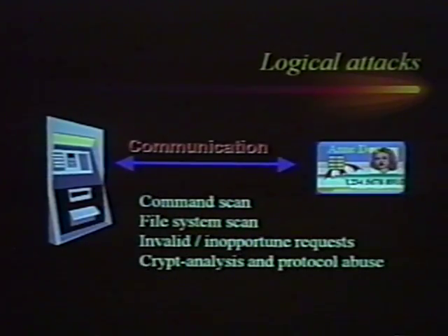Smart cards use binary coding of commands, and there are just 2 bytes allocated for indicating the command. So you can exhaust these 2 bytes and try all 65,000 possibilities. Often you'll find that there are commands supported which are not in the spec, and these are maybe proprietary, used for testing purposes or whatever.